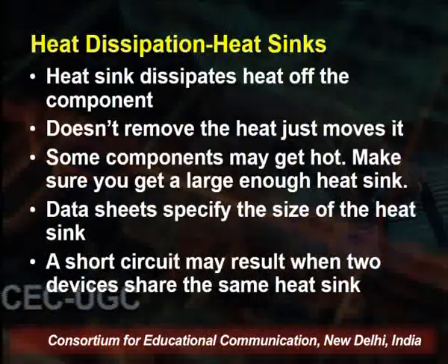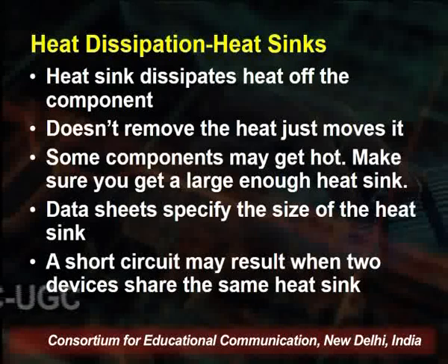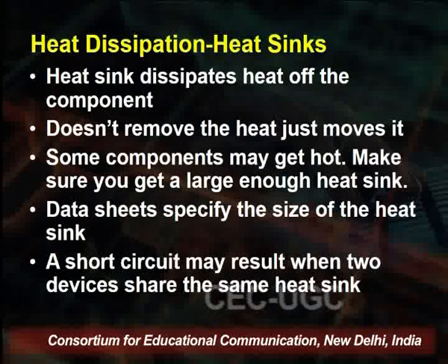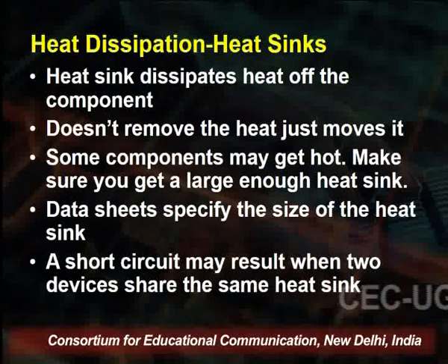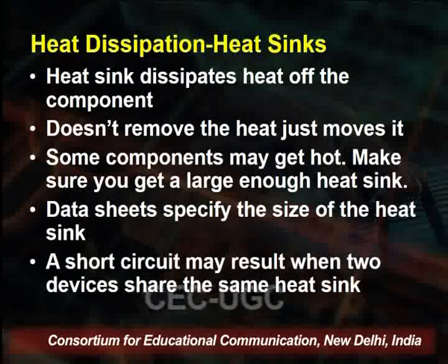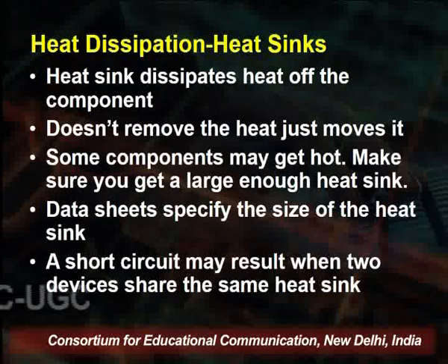The next point to keep in mind is the heat dissipation or heat sinks in PCB designing. A heat sink dissipates heat from the component and does not remove the heat, just moves it, and some components may get hot. So make sure that a large enough heat sink is used in this PCB. Check the data sheets, especially for the size of the heat sinks, so that the heat of the component is dissipated. A short circuit may result when two devices share the same heat sink.